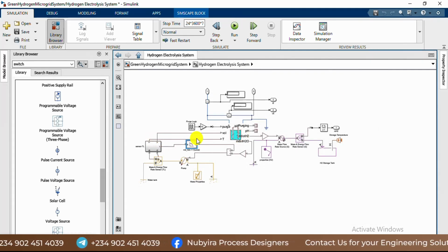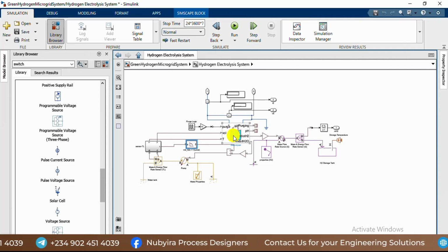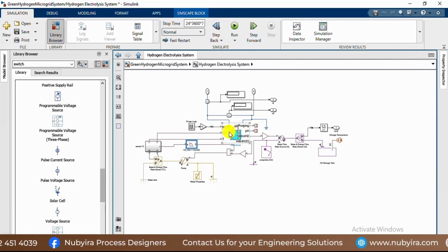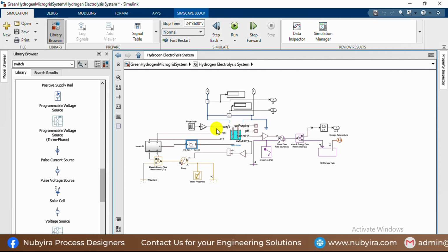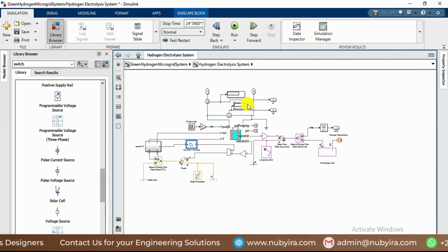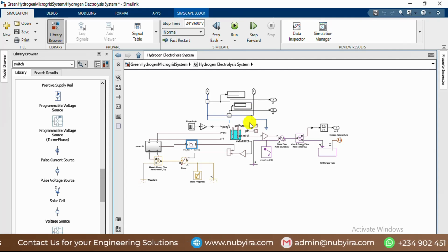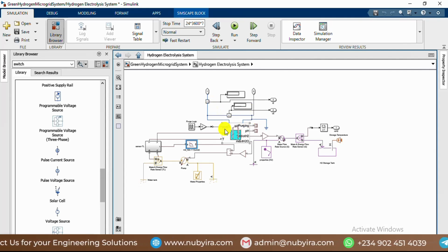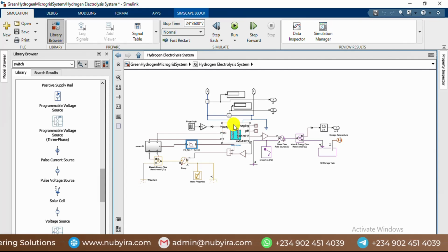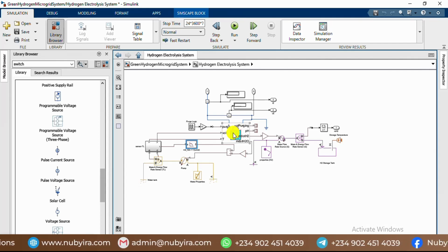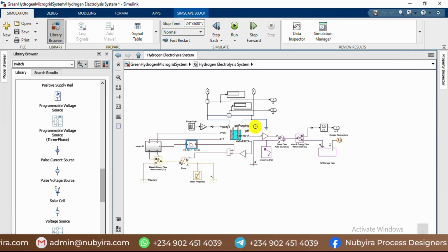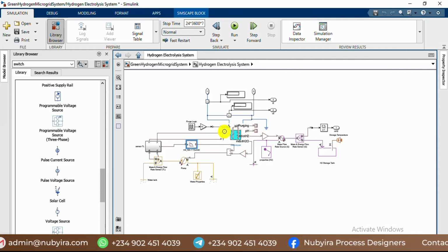Then you have the temperature of the water is sent to this electrolysis stack. The volumetric flow rate is also needed, that is sent to this place. So for the generation of hydrogen, this block will take the voltage that you have supplied from our bus and the current, and this purge block if there is any excess accumulation of inert in the system. You understand? And the pH value, I think we are not using pH value and volume of purging because we are not purging, basically.